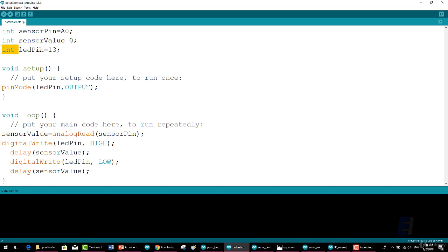Then, int ledPin = 13; Once again, the term ledPin is not a reserved word in Arduino. It was chosen to describe which pin was connected to the LED. The value 13 is a normal value, but just like A0, when used in context, it represents pin 13. However, you will need to add the following code under the void setup: pinMode(ledPin, OUTPUT); which is used to declare the LED as an output.